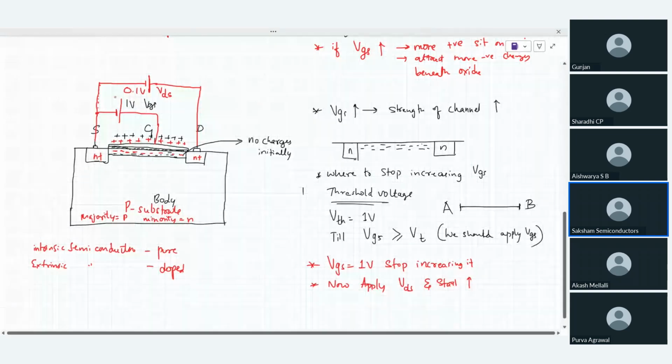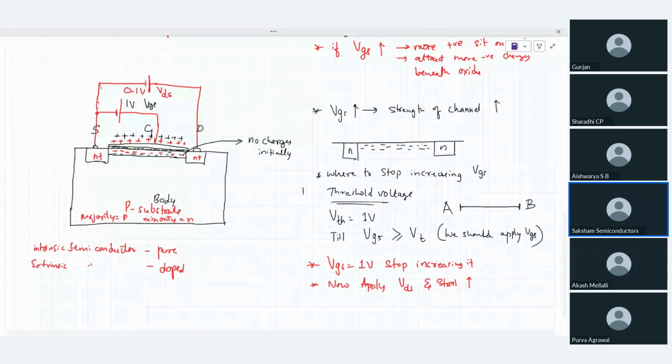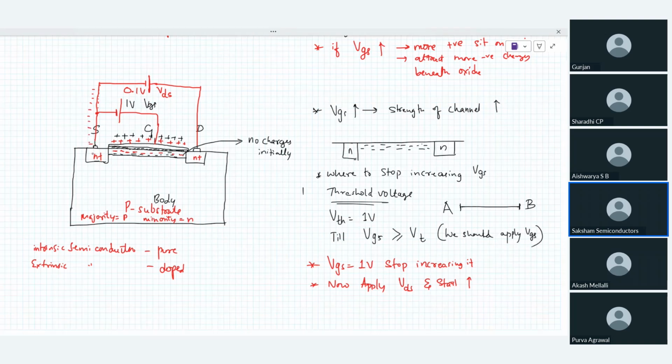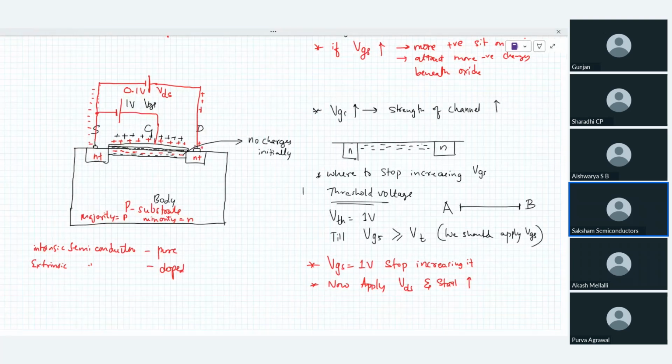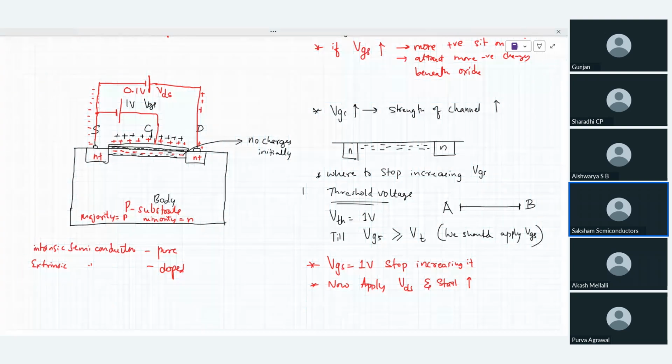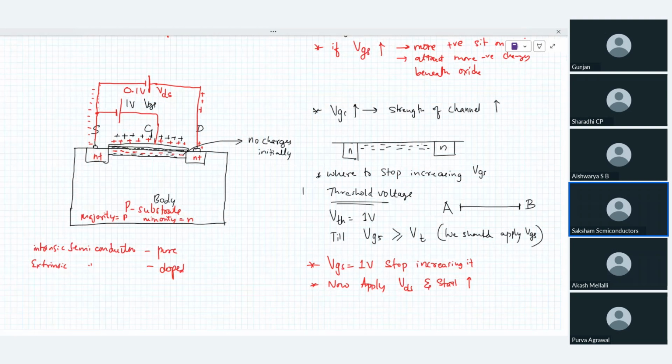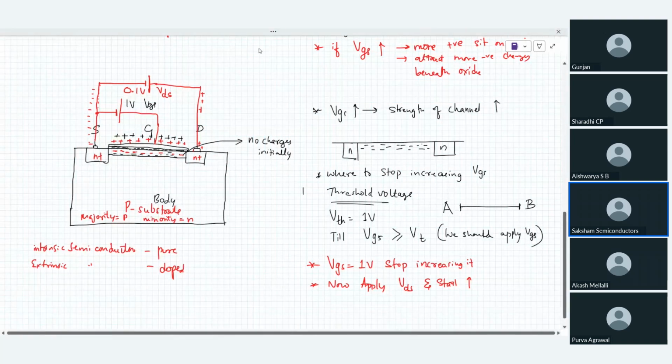When you apply this particular voltage, again, 0.1 equivalent amount of electrons come through this wire and get accumulated in this source region. And 0.1 equivalent amount of positive charges come and sit on this metallic layer. And again, sometimes through this metallic layer, because there is no oxide layer, they may go inside this N plus region and some neutralization may happen, right? So all those things are there, but in due course of time, positive charges are sitting on top of this metal layer, and there are negative charges over here. Now, very interesting things are going to happen over here. Let us try to understand that.